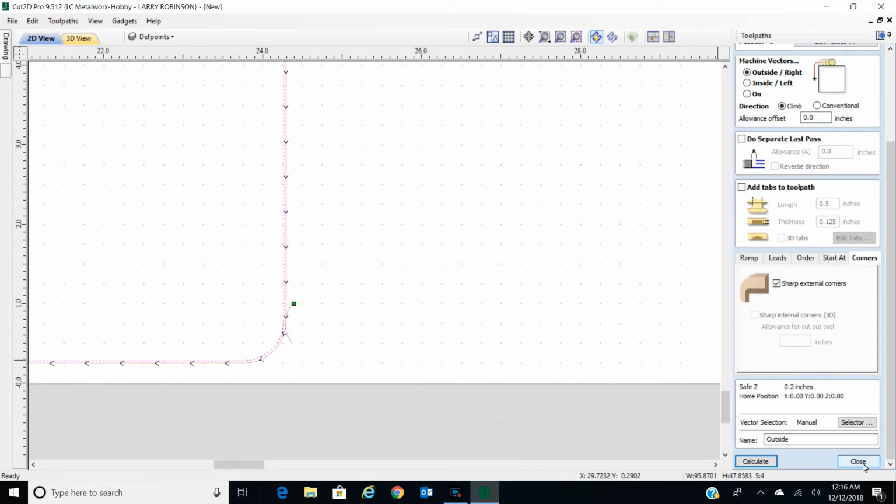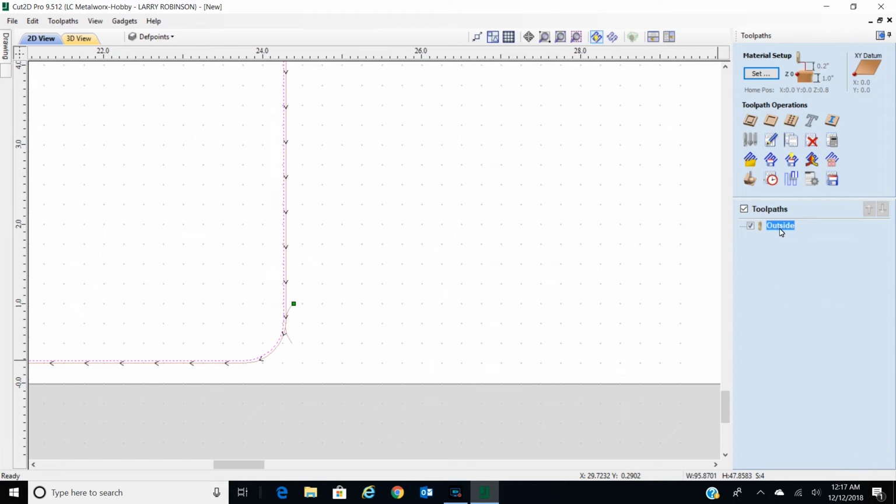Okay, so then we can close that, and there's our tool path. If you hover over that, you can see it says that tool is 85 inches a minute, and what else does it say? It's at spindle of 100. That really should be 100% feed rate, so it'll be at 85 inches a minute is what it's going to cut that at. That don't mean Mach 4 is going to cut it at that, because that's turned down. I usually turn that back up. On this simple cuts, you can run.